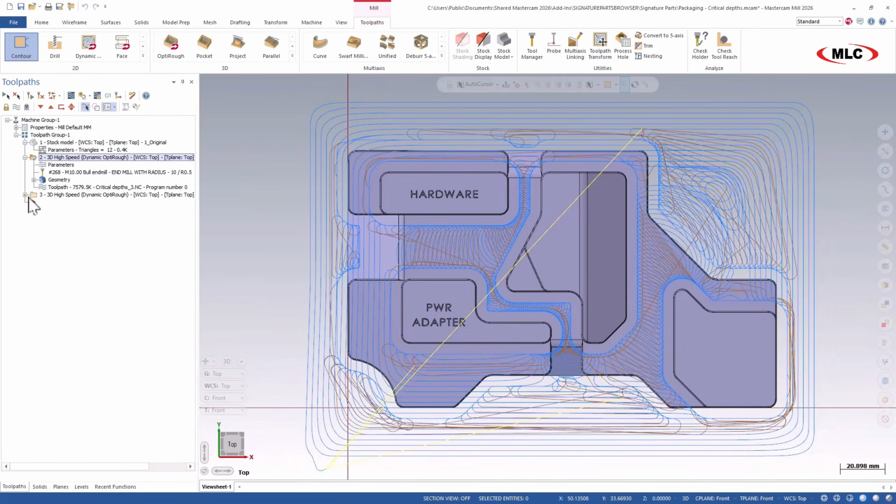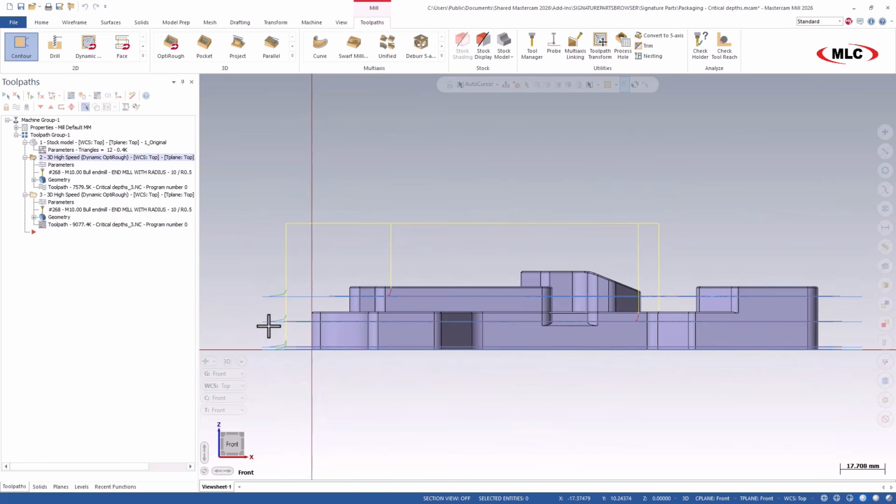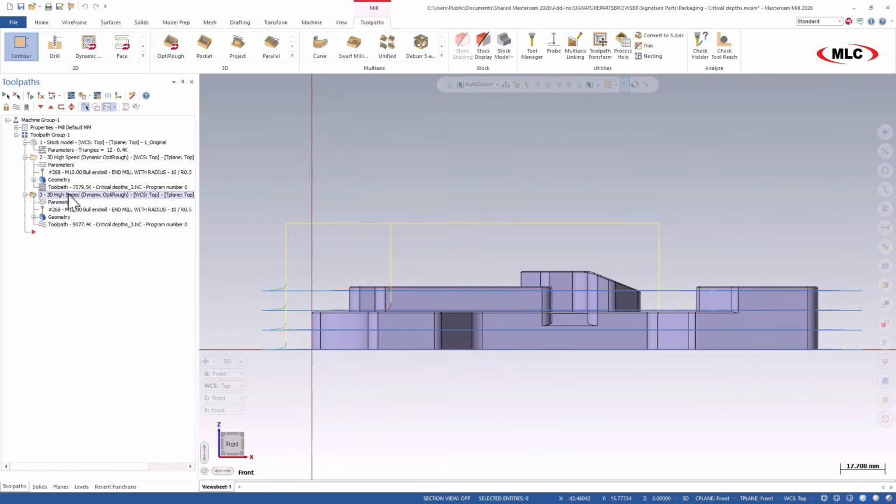So what we can do as an improvement in 2025, what they added last year, is the ability to create those uniform step downs, right? And that helped. Notice how we have these 4 step downs. That last one has just a little bit left. And I turn on the uniform step down, it equalizes those step downs. And yeah, it addresses one of the flats, but not a couple other ones here.